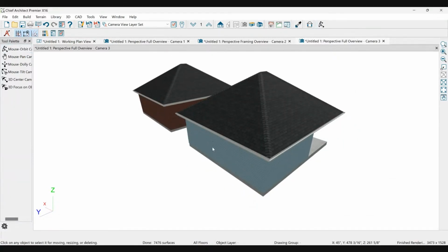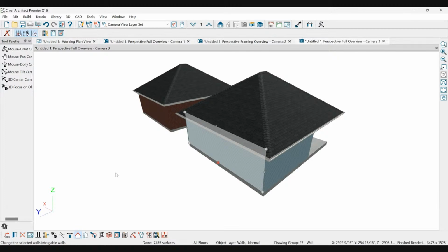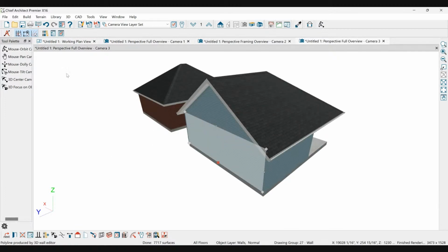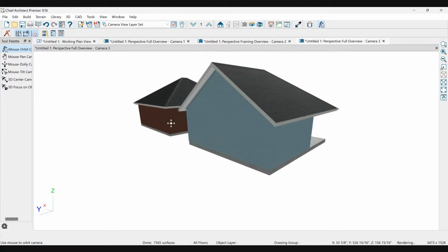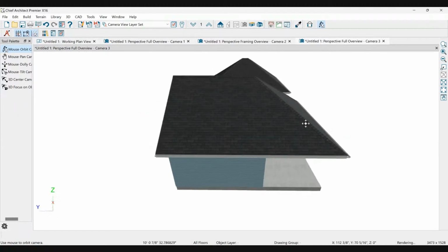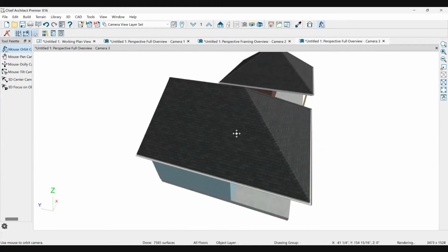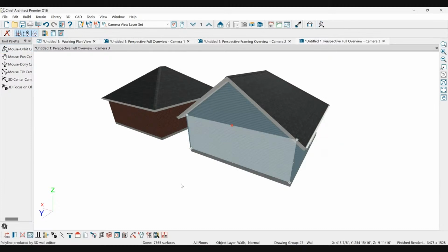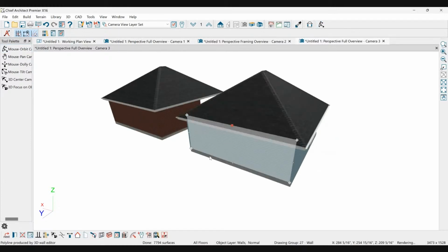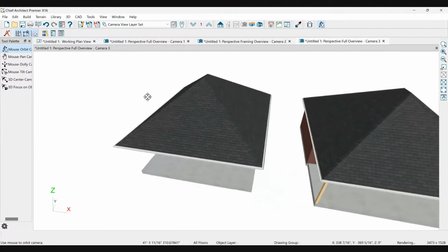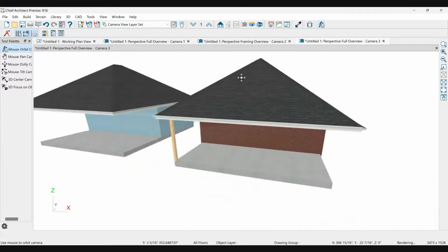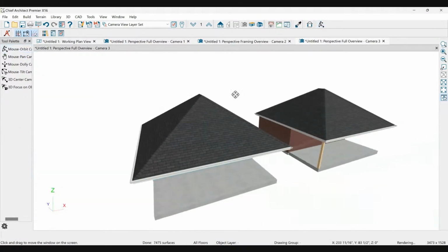If I were to grab this wall and say, you're not a hip wall, you're a gable wall, now it creates a gable end like this. And you're used to seeing this kind of thing with houses in America anyway, because this is how we've built lots of stuff. If I put it back to being hip, then that's what the roof does. So that is what the roof is doing for both of these, because that's just the way I set it up. Nothing special there.